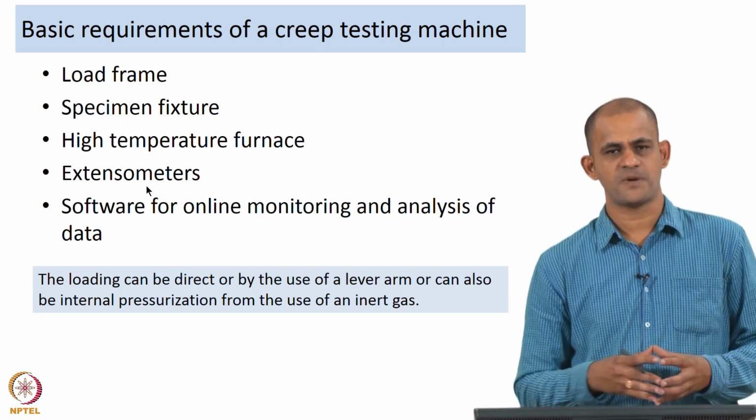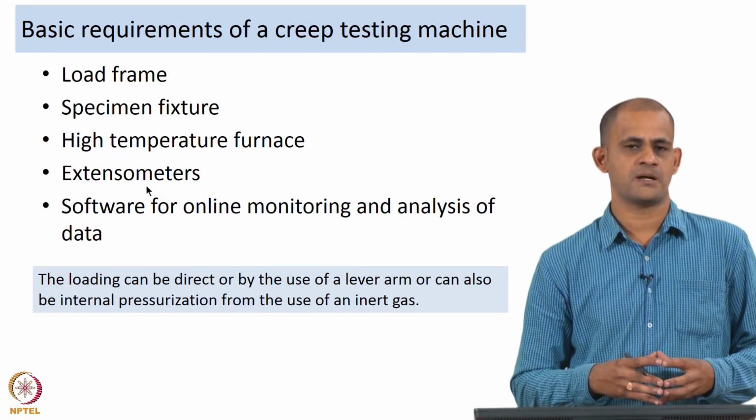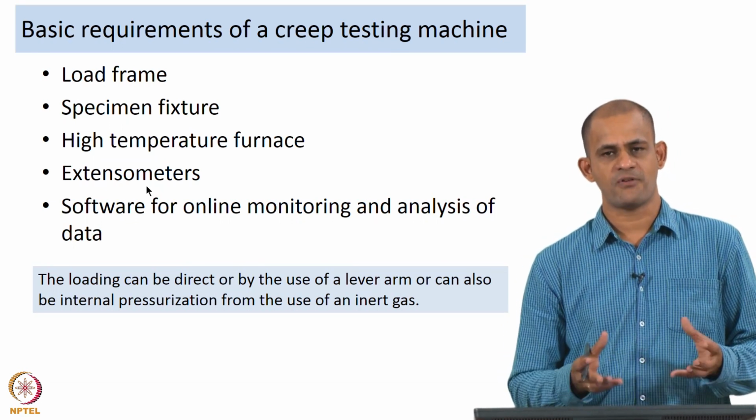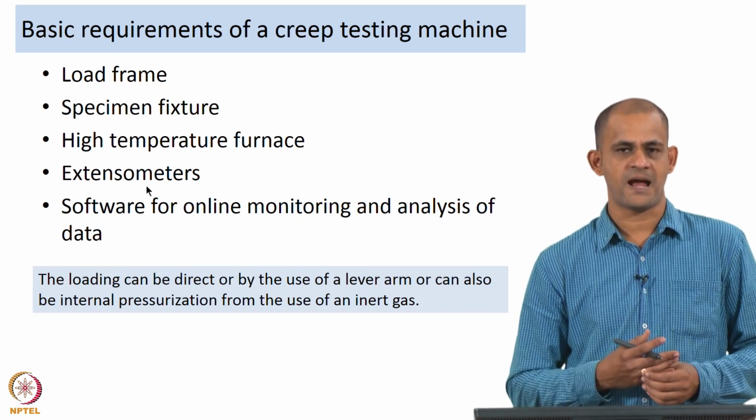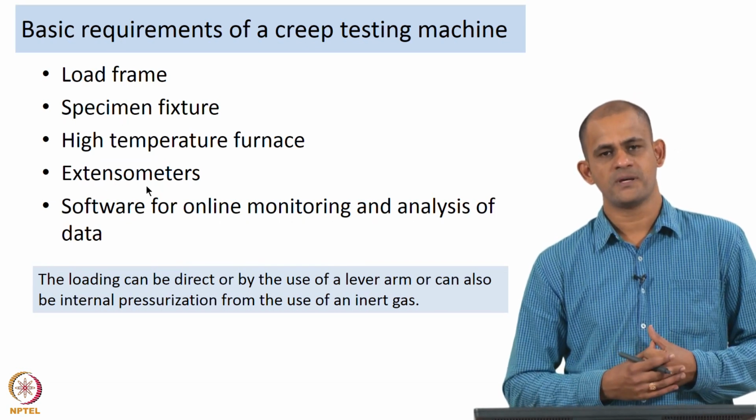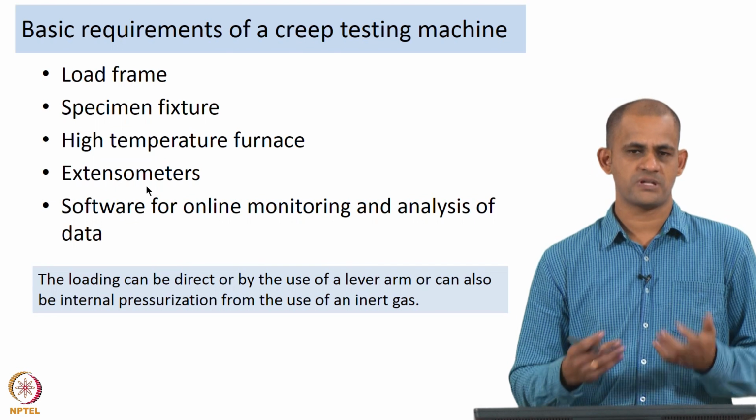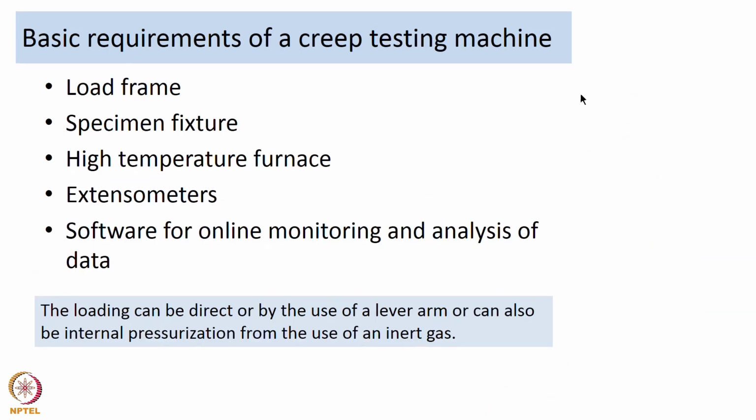The latest creep machines also have software which allows you to monitor the deformation continuously, and some of them are also capable of analyzing the data generated. Say if you are generating a strain versus time curve, the software is also capable of analyzing the data and giving you the strain rate of deformation, things like that. And like I mentioned earlier, the loading can be direct or can be transmitted to the sample by using a lever arm.